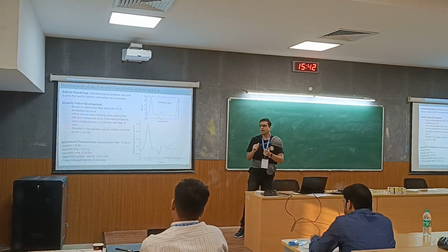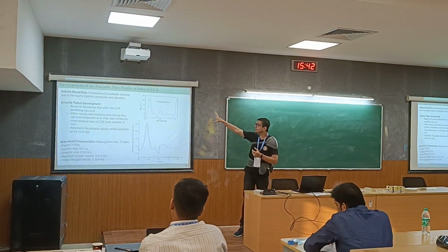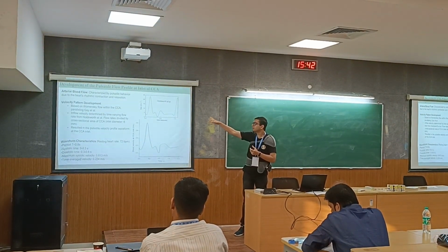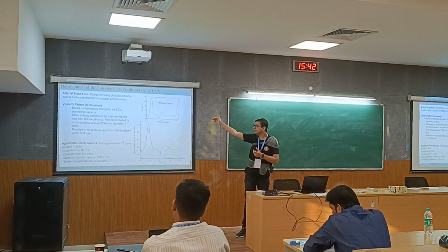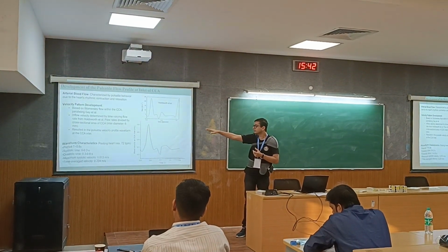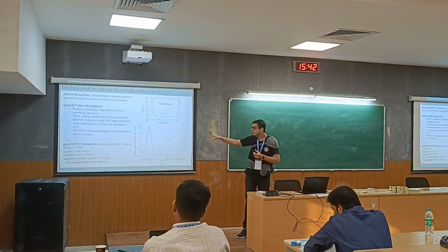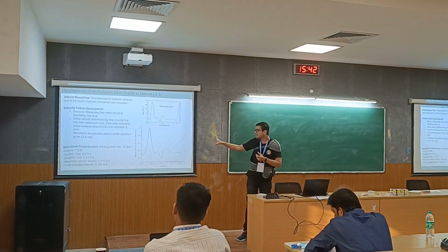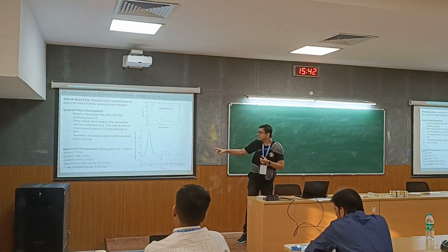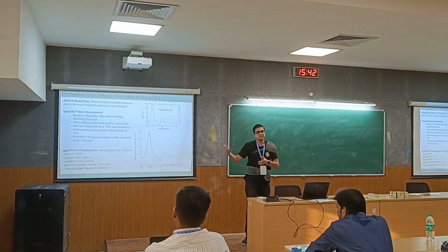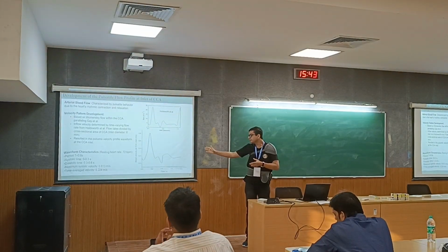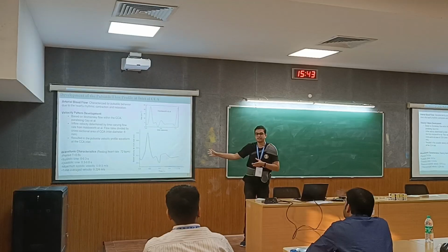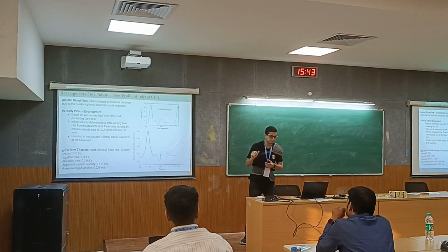is inaccurate. What we tried doing was taking actual flow data from this study, and we divided it by the cross-sectional area to obtain the velocity. From the flow rate we obtained the velocity, and that we put as the inlet boundary condition here. So this gives us a more realistic insight. We took the systolic time as 0.3 and extended it to the diastolic time from 0.3 to 0.8 seconds. That's the total cardiac cycle time.